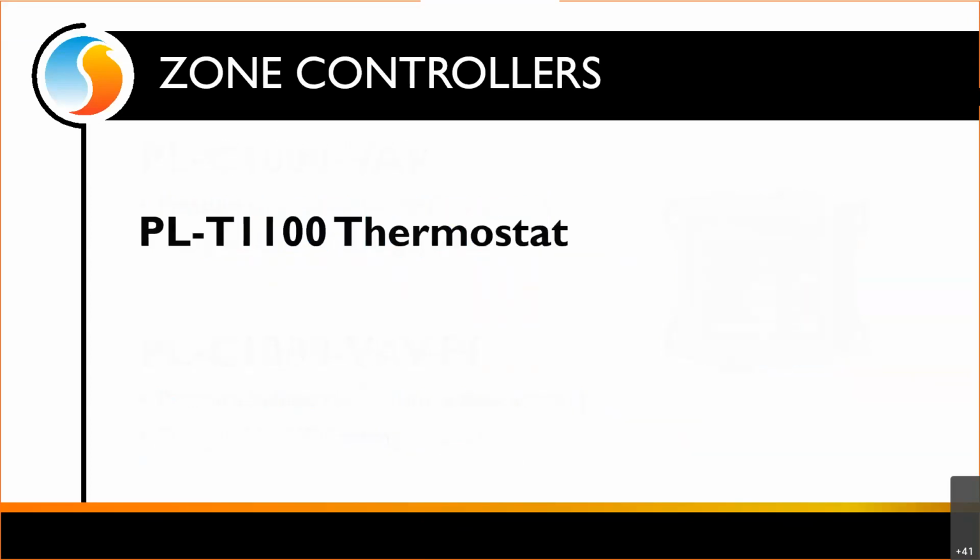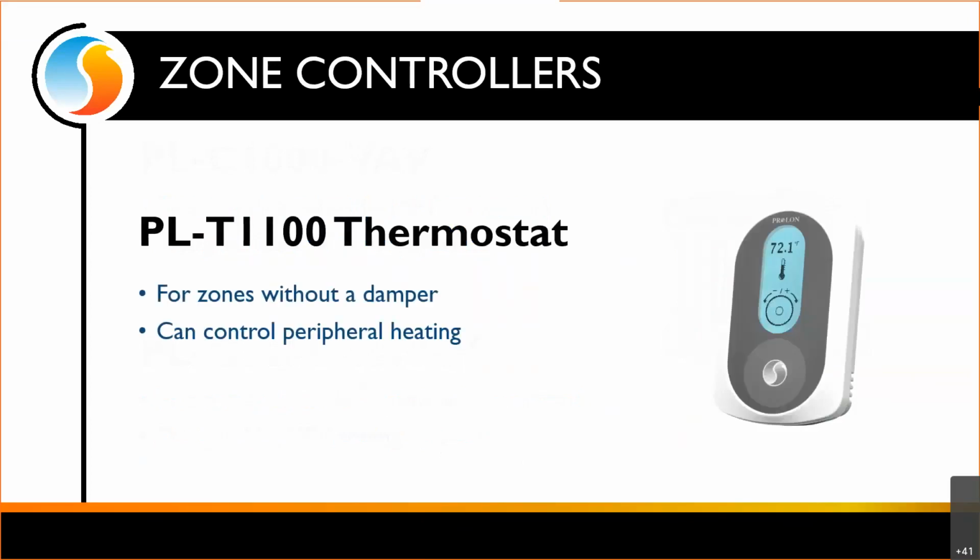And then lastly, in terms of zone controllers, it's important to bring this one up because the T1100 thermostat can act as a zone as well. Now, the idea behind this is that sometimes in some systems, maybe we've got a dozen zones with dampers, so we'll use either the VC2000 or the C1000. And maybe there's another space which doesn't have a damper. However, we still want it to be included in the heating and cooling load calculations, which is driving the unit.